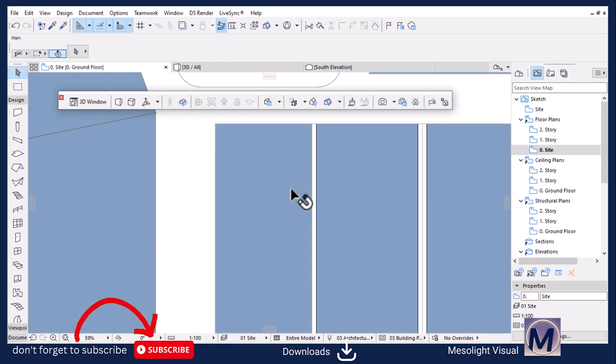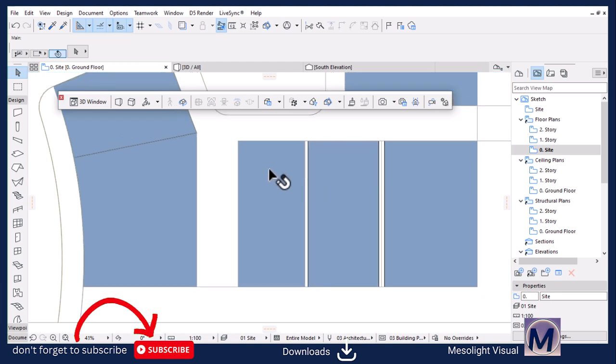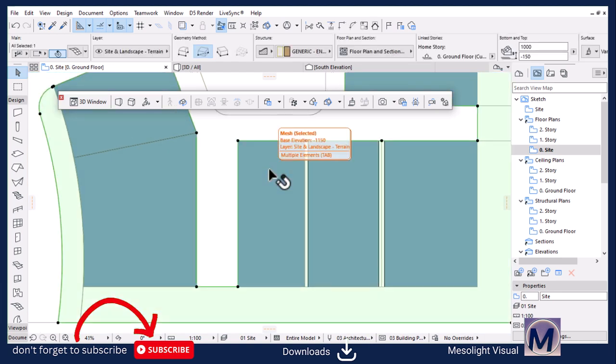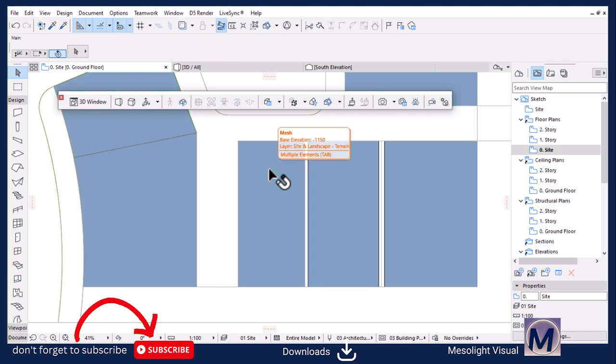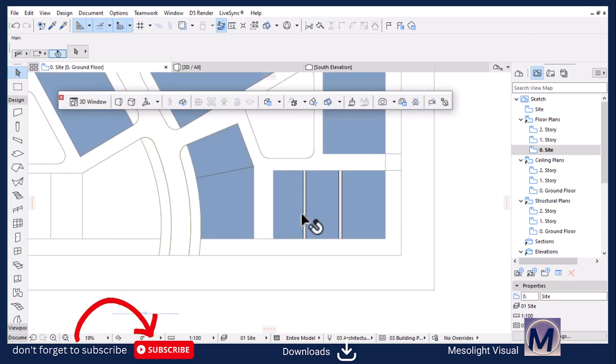In a situation where you have too many things sitting on top of each other, it's very important to understand the selection criteria of ArchiCAD. In this case, I want to select the zone, but you see it's picked the terrain, which I don't want it to do. So let me escape. If you hit Tab, it keeps on picking or highlighting the elements like that. You see, now it picks my zone. I can select the zone and then offset the edge by 500 like that.